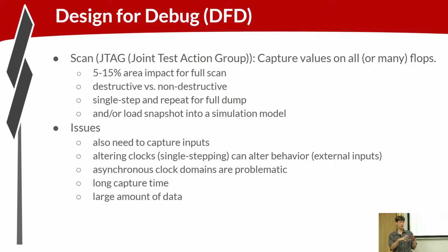Scan creates a chain through all of your flip-flops by which you can shift out all of the data stored in those flip-flops, right? So if we do full scan, that means every flip-flop is part of a scan chain. Then we can run the CPU, freeze the CPU, and run